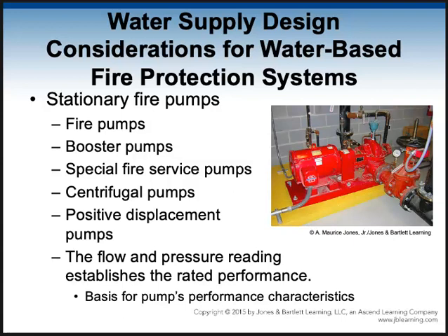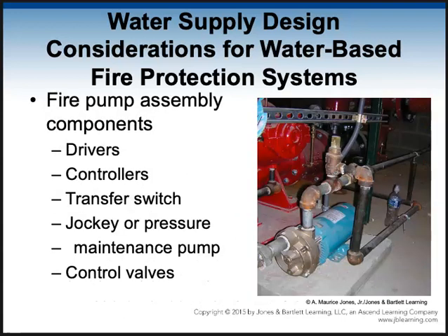So there's fire pumps, booster pumps. They're usually of a centrifugal type where they increase the pressure and add to it. Sometimes they might use a positive displacement pump, and we'll talk about the difference in them later on when we talk about pumps. But they've got to get adequate pressure to the different parts of the building, if it's a big building or a high building.